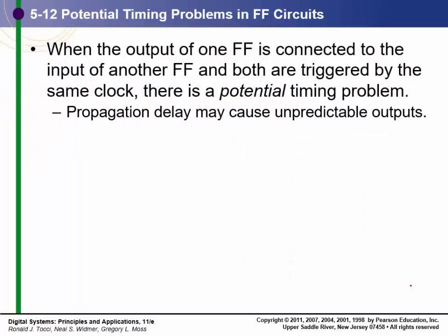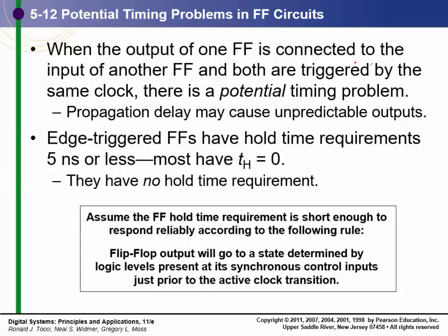The input of another flip-flop is triggered by the same clock. That's their propagation delay. This is what we're talking about when the output is connected to the input of another flip-flop by the same clock. You have a timing propagation. Again, that's usually not a problem because most edge triggers have hold times. This is the key: the hold time is usually 0.